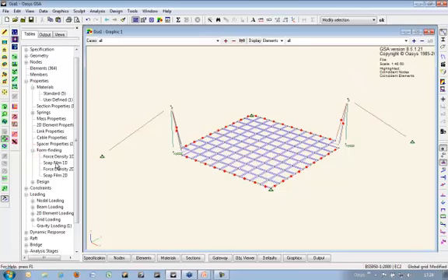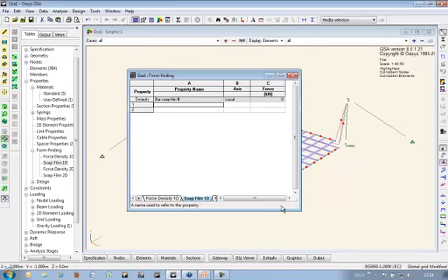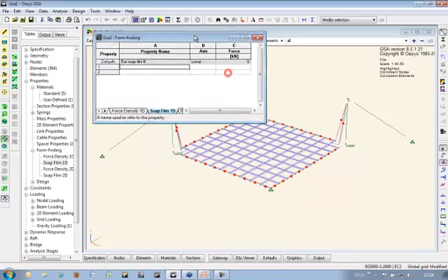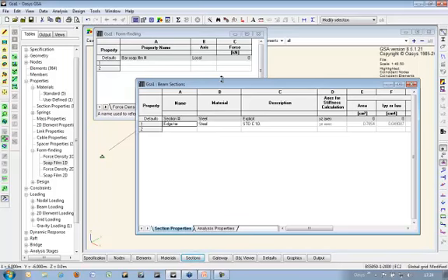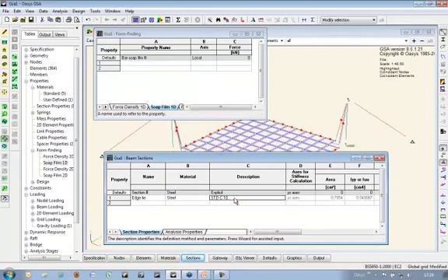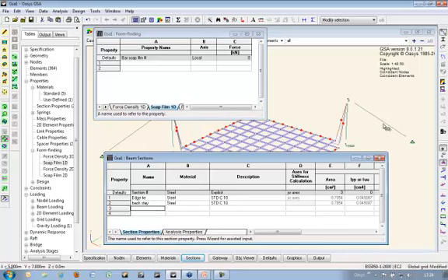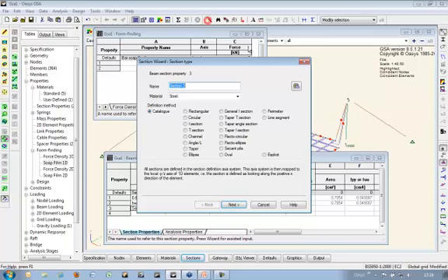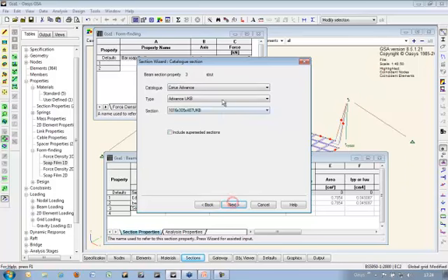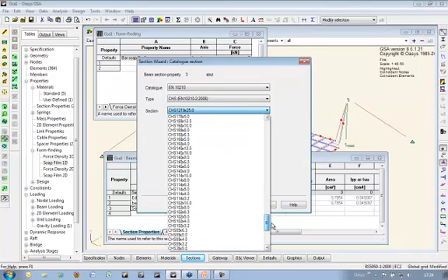So form finding properties now. The soap film 1D properties. Now these will match up with the section properties. Now we haven't defined these yet. Let's take this 10mm cable, copy that down to there, and that is going to be my backstay. And I also want, so those are our 2 backstays there, and the third one is going to be my strut, and I'll use a catalogue hollow section, let's say about 100mm diameter.